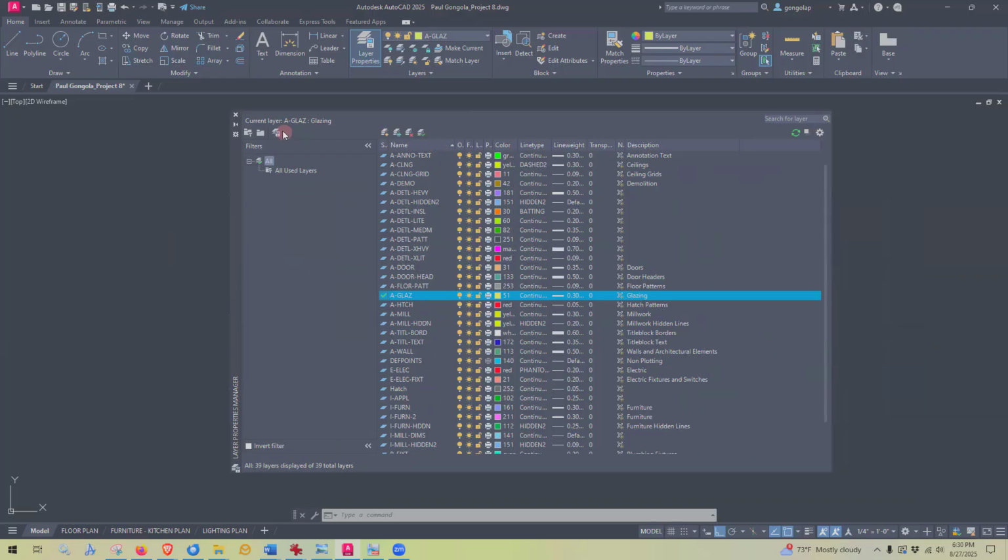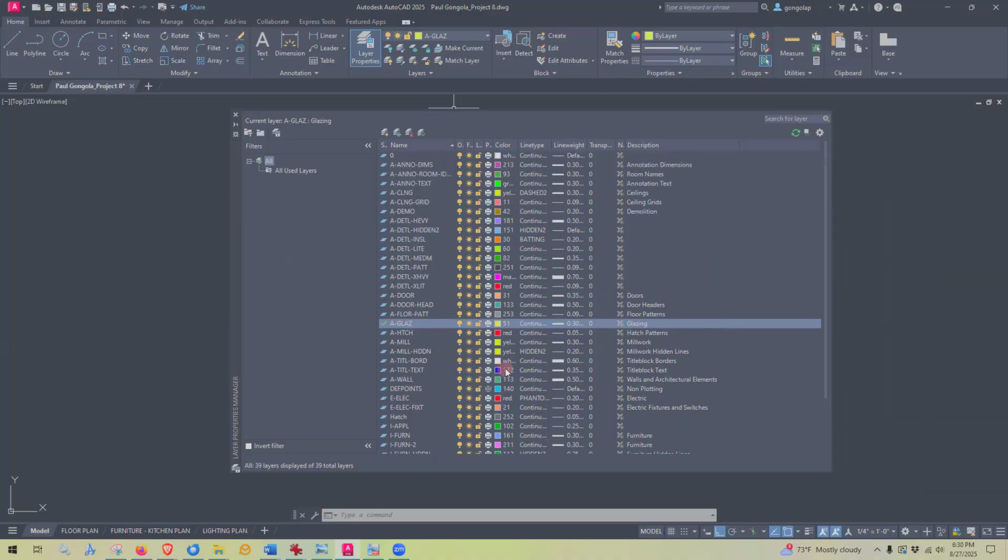And then I can come back and put them back to their default position without having to find each layer that I froze and then thaw it. So I'm going to create a layer state of all of my layers as they are right now, whether or not they're frozen or locked or whatever state they're in right now.